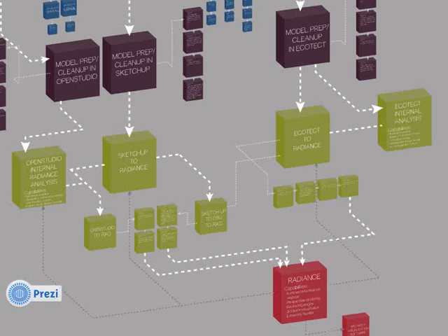So, for instance, OpenStudio is gaining ground in terms of its ability to conduct daylight analysis. There's a button within its interface that runs it with Radiance, so you're getting a format that will export all of this automated, go into Radiance, come back into OpenStudio, and give you some very powerful information. It does annual simulations. There's visualization capability directly within OpenStudio, and you get annual metrics as well. But not really visualization or perspective renderings and stuff like that, right? So it's good for a certain type of analysis.